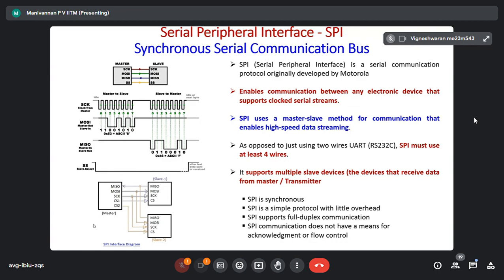You want to do service. You can never switch off the telephone exchange because there may be 10,000 lines, correct? So at that time, the circuit is designed such that even without switching off the main power, you can pull out the board which failed and put in the new board. While doing that, the circuit should not fail. The new board you are inserting should not fail.